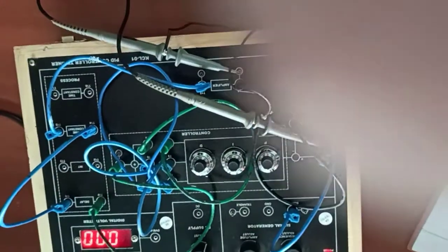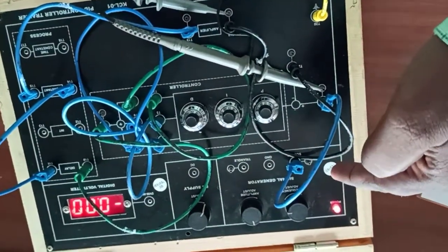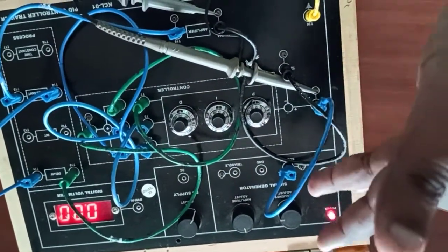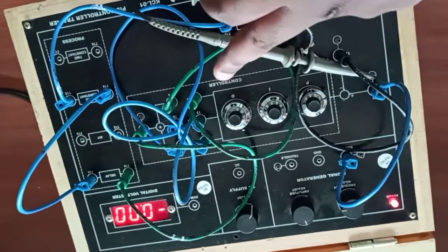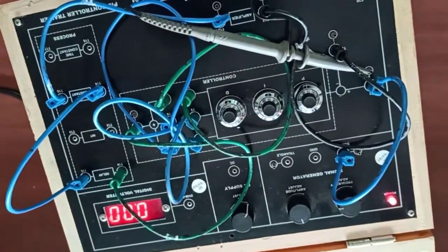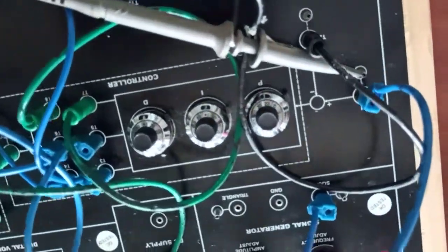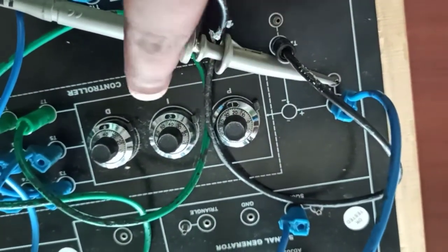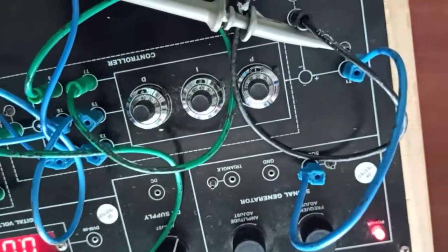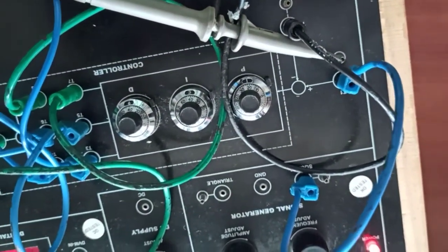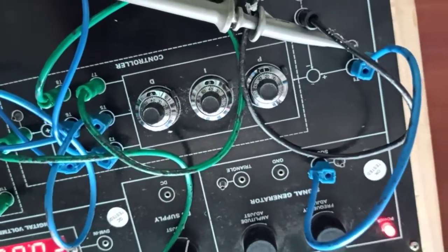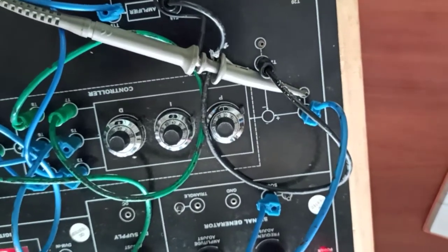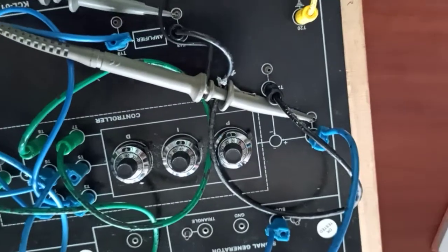This is how the experiment is going to be done, and here we have the kit for this experiment. There is a square wave generator point, or we can also use a triangle generator point. This is given to the input of the circuit, and there are three knobs to adjust the different gains, that is Kp, Ki and Kd. The standard values are given by the manufacturer: 1 rotation with the value of 20 for Kp, 3 rotations with the value of 40 for Ki, and 6 rotations with the value of 40 for differential gain. The combination of these three values gives us a better stabilized output.